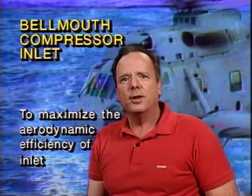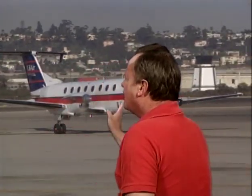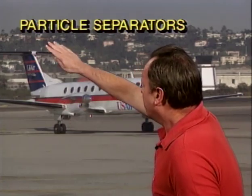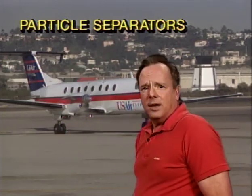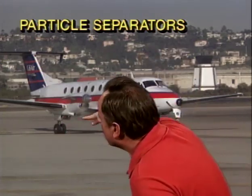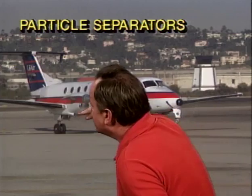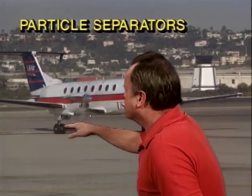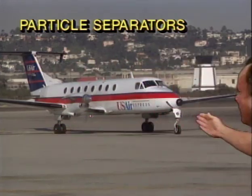Now, another problem that you have is FOD that we talked about earlier. You can get FOD when the engines are mounted near the ground. Turboprop engines very often have FOD problems, so they install the engine with a bend in the airflow going into the engine. Helicopter engines have the same thing, and that is what is known as a particle separator. Particle separators separate sand and ice and give clean air to the engine, and they function by utilizing a sharp airflow directional change or bend to take advantage of inertia or centrifugal force, and that filters the air to the engine. And sometimes they also have air filters and inlet screens, but particle separators are a very big way of making sure you don't get FOD in these turboprop engines.